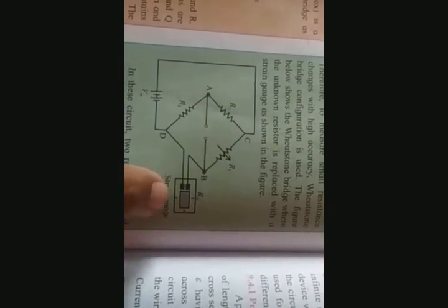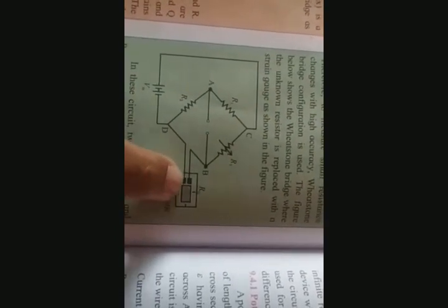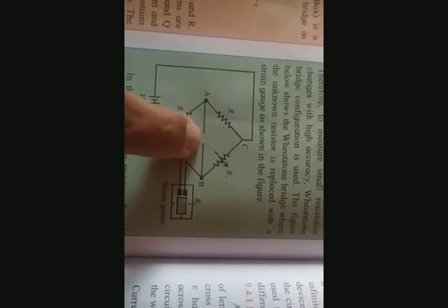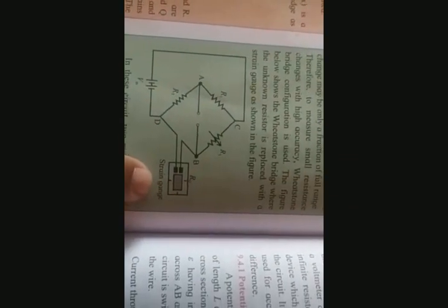Whatever the measurement change here, when the strain gauge is applied for some measurement, its resistance gets changed, and it will change the value of voltage across these 2 points. Measure this voltage, and you can find out the strain produced in that material or particular thing, and that is strain measurement by using the bridge. That's it. So students, this is the topic that we have covered up till now, which depends on the Wheatstone bridge network and meter bridge and its application.